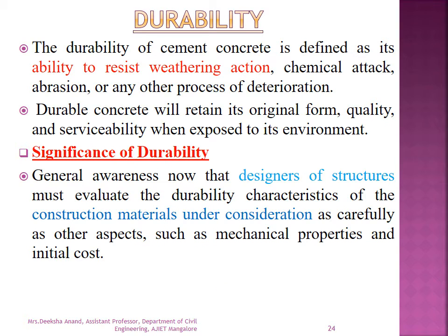So next, coming to the durability of the concrete. What do you mean by durability? Durability is nothing but being durable. If we take the common term durable, it is how long it can resist. The ability to resist weathering action is known as durability. Durability of cement concrete is defined as its ability to resist weathering action, chemical attack, abrasion, or any other process of deterioration.